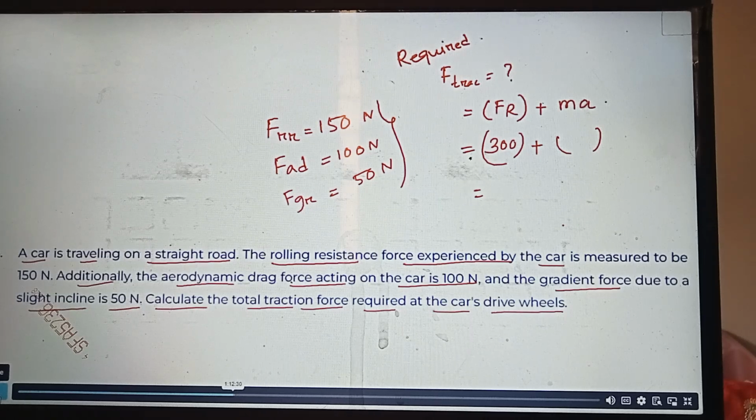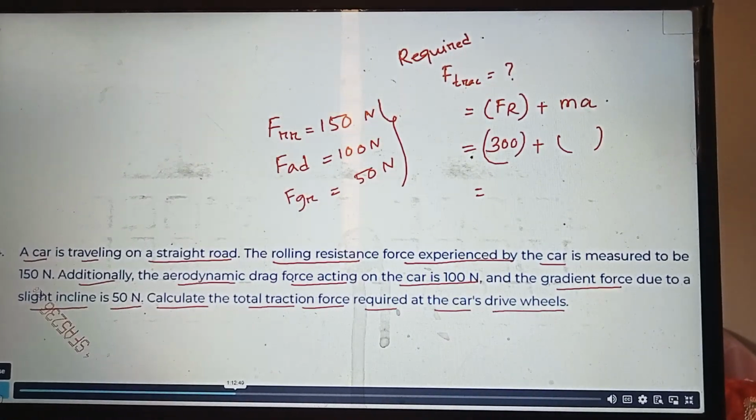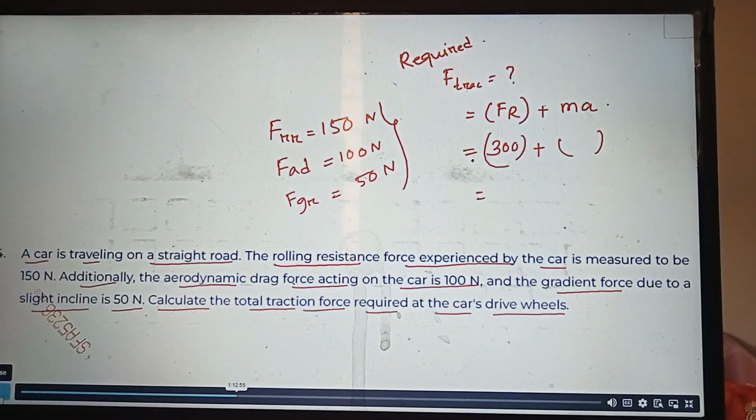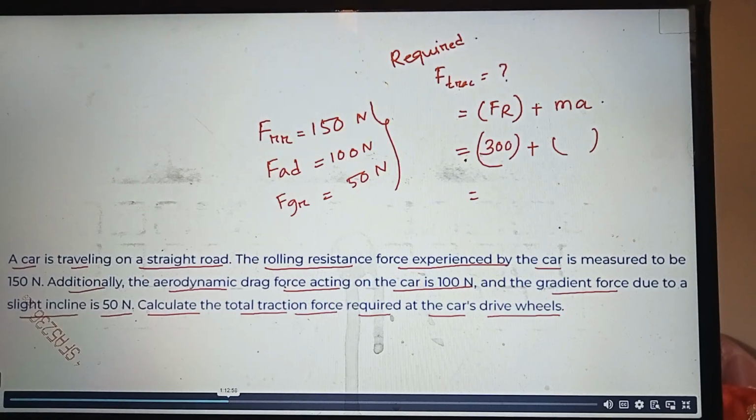So it depends on which vehicle you are doing it. For example, let's say a vehicle like Tata Nexon, right? Approximately mass will be around 1400 kg. For any vehicle you see their data sheet, you are going to get the information on mass, right? At the same time, the target acceleration, that also you know, right? Some vehicle they mention, as I told, 0 to 100 km per hour in 5 seconds. So from that you calculate this mass into acceleration requirement.